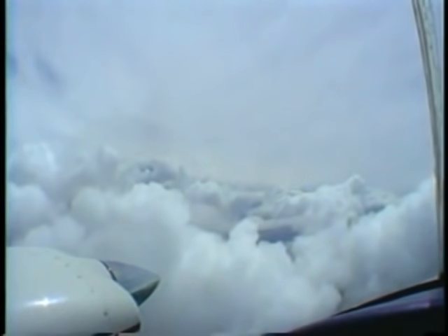Although the departure and arrival phases of instrument flight are often considered the most demanding, the en route segment can test your IFR skills just as easily. You must be able to combine your ability to control your airplane accurately using instrument interpretation with precise navigation skills, so your exact position is never in doubt.